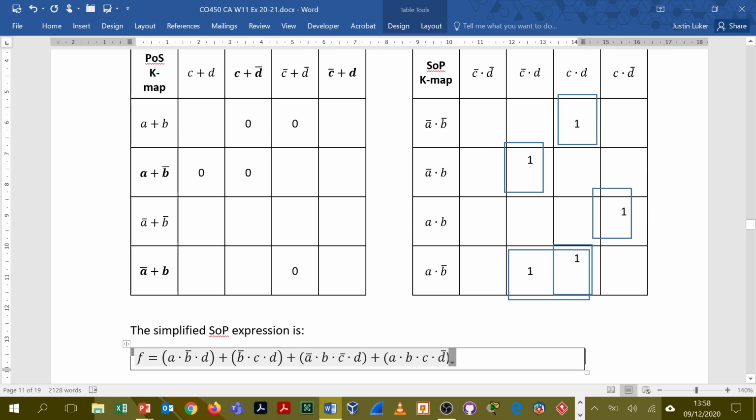So what doesn't change in this group of 2 here? Just group those up so you can see them. So what doesn't change? A or B remains the same because they're in the same row, and then you've got C or not D, or not C. So C changes, so we get rid of C and we're just left with not D.